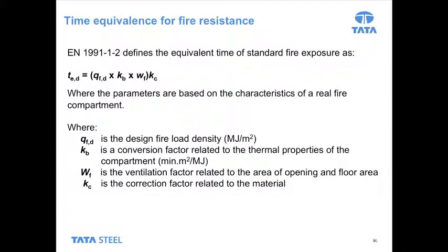So this is the equation for the time equivalence from the Eurocodes. If we look at the UK National Annex, it very helpfully says that we can't use that equation, and it points us in the direction of something else, a PD document, PD 6688, which adopts a slightly more complex approach. But nevertheless, the Eurocode approach has become a standard part of modern fire engineering. It looks a bit complicated, but in practice it's relatively simple to use. But perhaps the most important point to make is that it requires a little bit of knowledge and expertise in order to know which values to choose for entry to that equation.